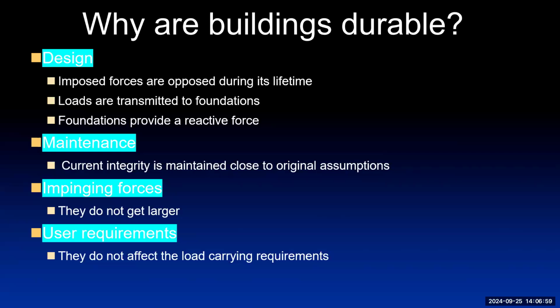Secondly, the loads must ultimately be transmitted to the foundations. If they're not, then there are loads which will do damage. Thirdly, foundations provide a reactive force. What are we dealing with here? It's Newton's third law of motion: all actions have an equal and opposite reaction.